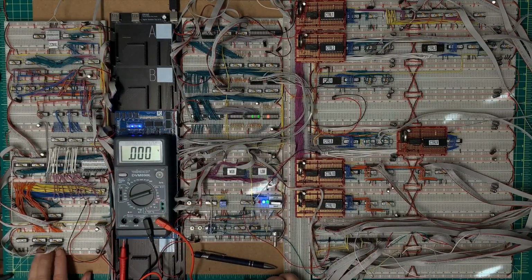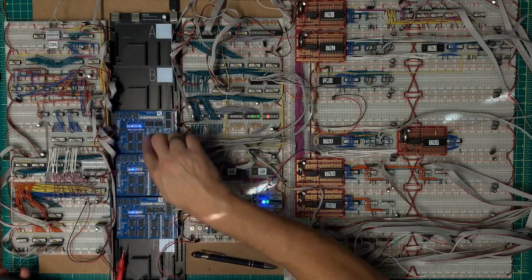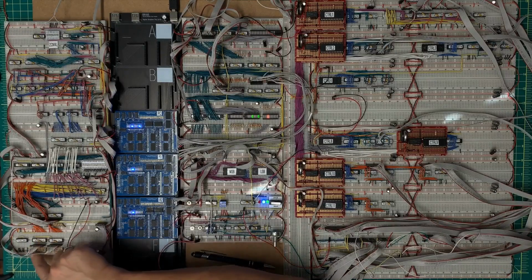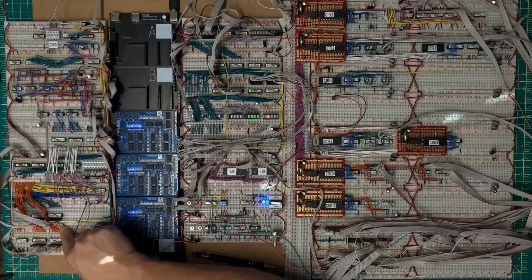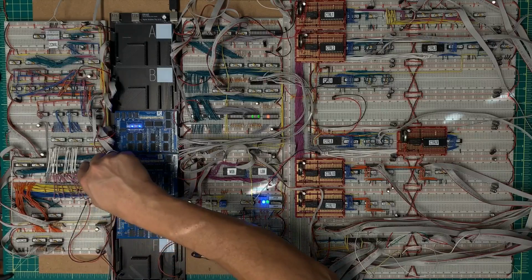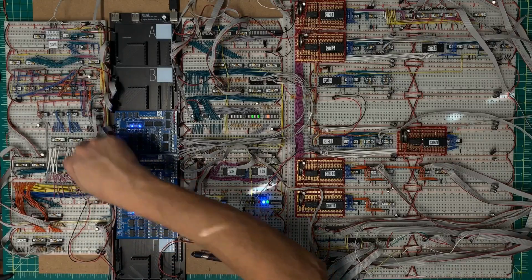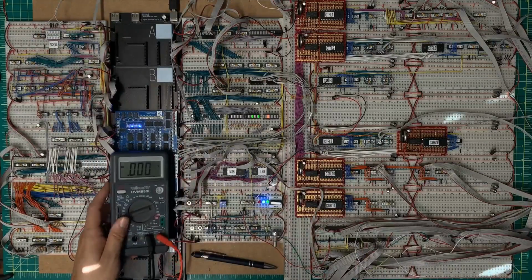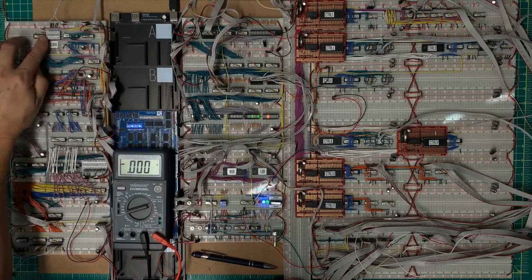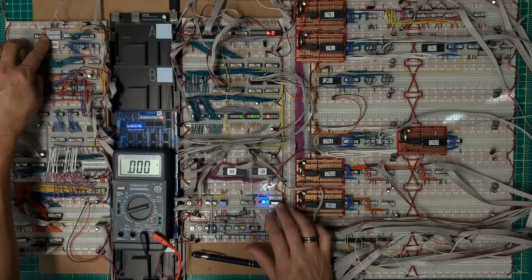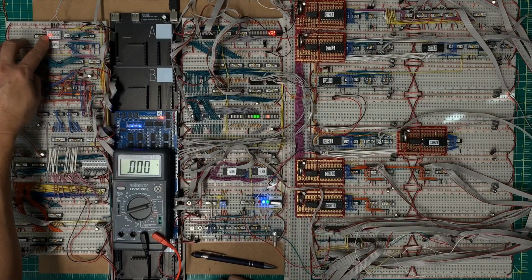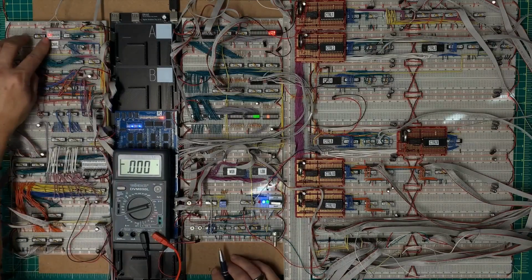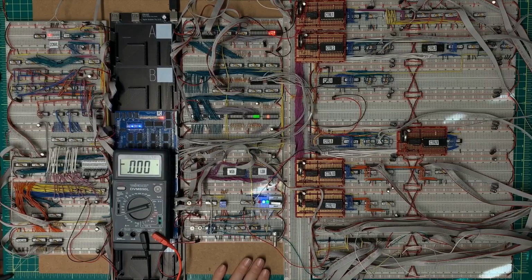Okay, now when I reset, nothing is asserting out onto ALUA or ALUB. Therefore, these are being pulled low properly by the 10,000 ohm resistors, meaning I'm adding 0 and 0, and the result is 0. Now, what I don't have is a proper latch up here that the 0 flag is coming on. Okay, that was an add of 0 to 0, which does indicate the 0 flag. So that is good.